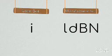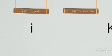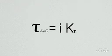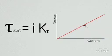We will group all of these variables that are set by the manufacturer into one term, k-tau, the motor torque constant. This is a parameter which will be supplied by the motor manufacturers, and it says that the average torque produced in the motor across a single rotation will be the current times this one constant. Therefore, the torque our motor can produce is only limited by the current we can run through it.